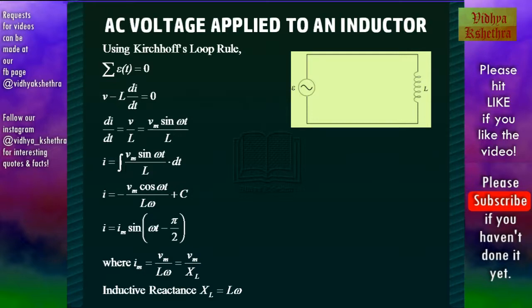Now to get the value of current in this circuit, small letter i, we have to integrate Vm sin omega t by L dt, which is negative Vm cos omega t by L omega plus C, where C is a constant. It can be found that the value of the constant is 0.